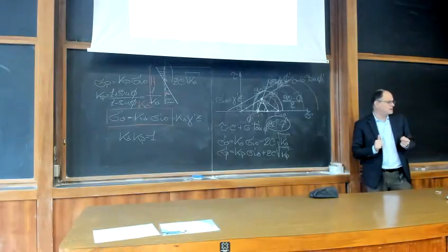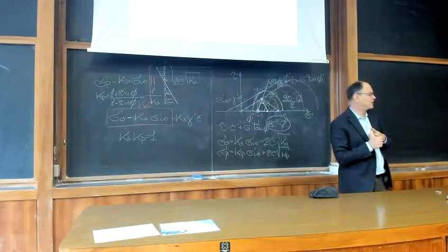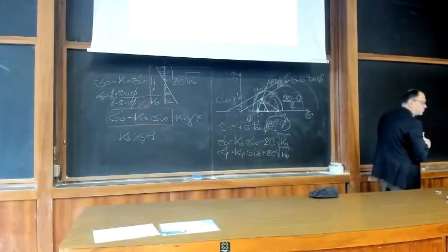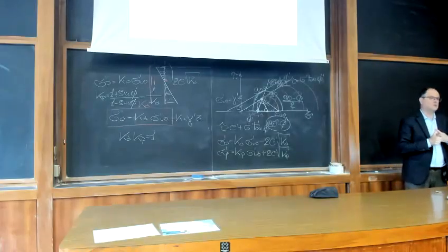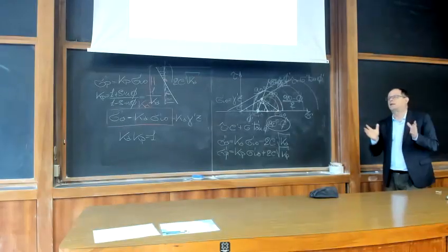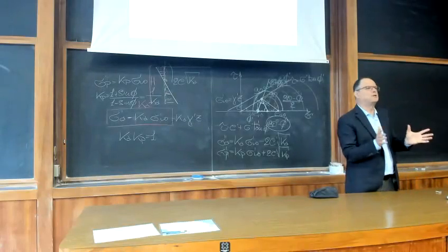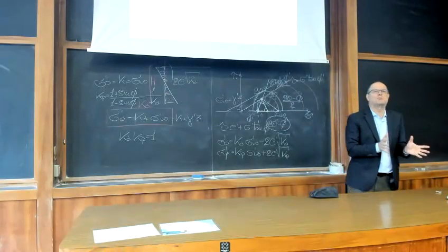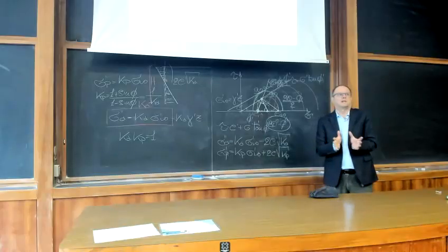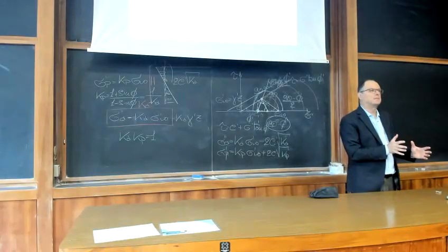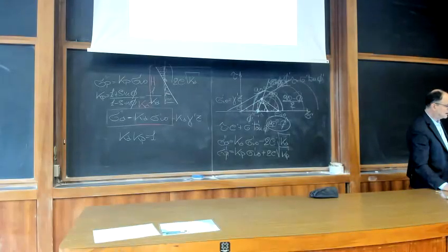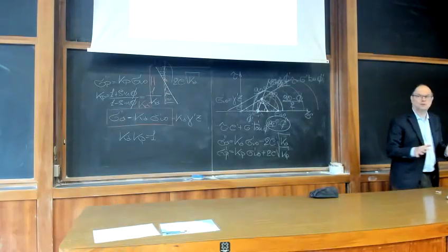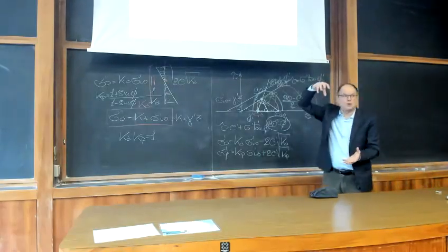Okay, you apply your foundation and you have two things. A foundation must satisfy two limit state conditions. The foundation must not collapse or become unstable under any conceivable loading. So typically we have always to design against ultimate limit state. What is the possible geotechnical ultimate limit state? Soil failure. So let's think, for example, that you apply the load to your foundation and then you measure the settlement of your foundation.